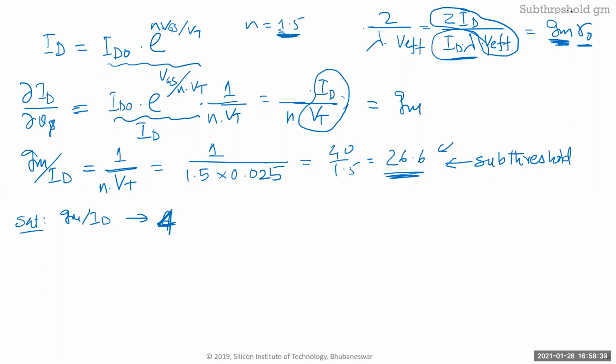In order to get GM higher, like I said, in your previous equation we just had V effective, right? That was the only thing we could control. But that V effective, you can push it to the subthreshold and get more juice out of that same amplifier. So you're not going to get more gain. You're going to get a gain of 40 because it's 1 over V effective. I can't go VD over 2, right?